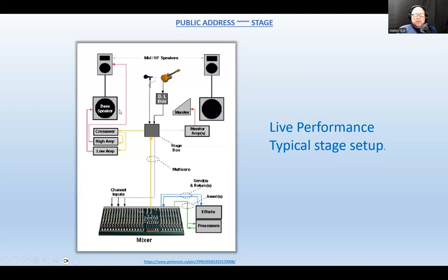Why is that? The reason is that the inputs of the mixing board could be within the range of more or less 600 or 800 ohms or 300 ohms or something like that. So it's in the hundreds of ohms. And if you consider the pure resistance of a 100-foot cable, you're going to have maybe sometimes 1 ohm, sometimes half an ohm.